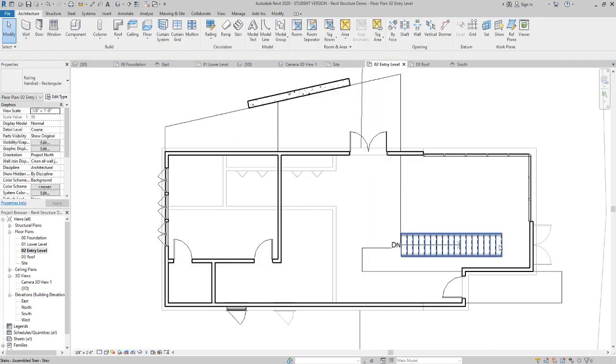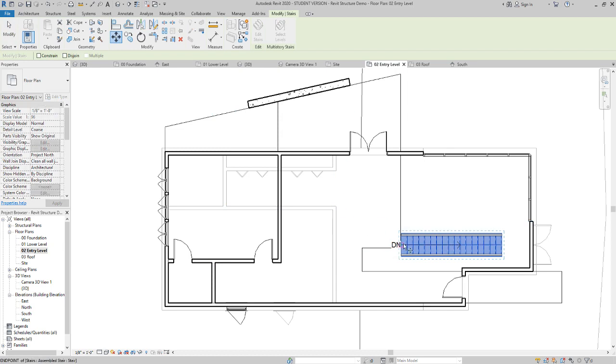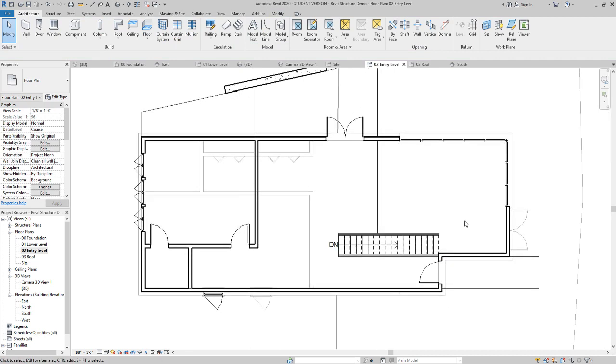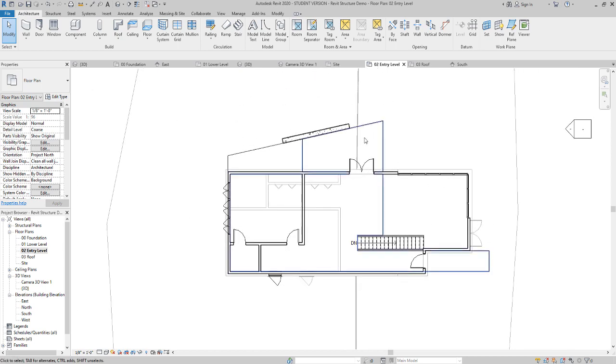And then now with these stairs, we can go and we can place these stairs right on right here. And I know it touches the corner, but that's fine. Okay, so then that's the stairs. And that takes us on to past page 48. Now we are dealing with these railings, and once again, if the railings crash Revit for you, just avoid them. I know that can happen. Alright, so the railing tool is right up here. It's really not too bad. They want us to create some railings that exist basically on the balcony.